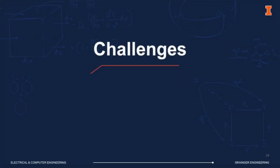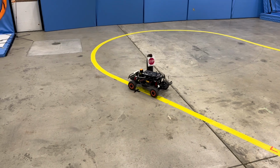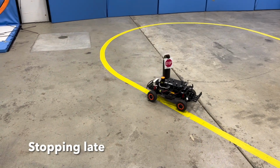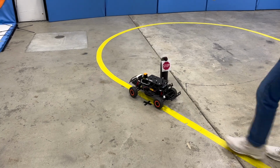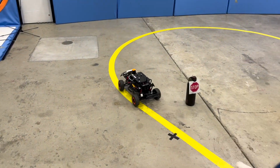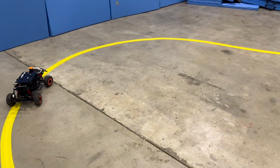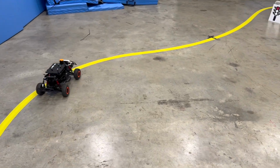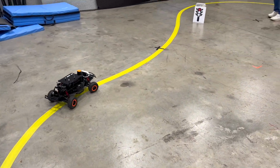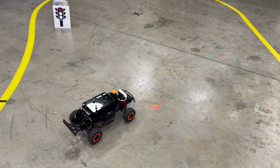Here we'll go over some of the challenges we faced during the development process. One challenge we faced was having the correct stopping distance. Sometimes it would stop too late and the motor would kind of wind up and it would slightly go backwards. To fix this, we fixed our minimum area detection threshold. The next problem we faced was in steering. So after large turns, it would overcorrect and continue to turn in that same direction without returning to the marked path. To fix this, we continually adjusted our PID values until we found a solution that would quickly adjust after large turns.